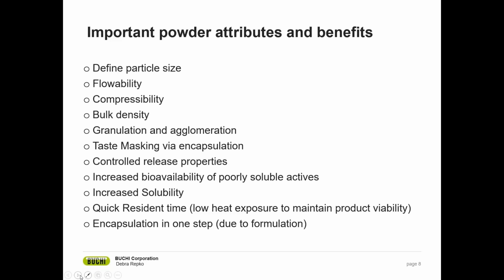So why would I want to do spray drying? What are the benefits and what can I do from basically a particle engineering perspective? First and foremost, I can design the particle size from my formulation. I can change the flowability, compressibility, and even bulk density of a given powder. I can do granulation and agglomeration of slurries.